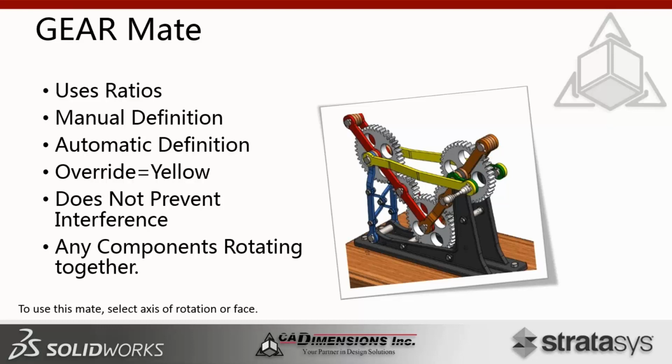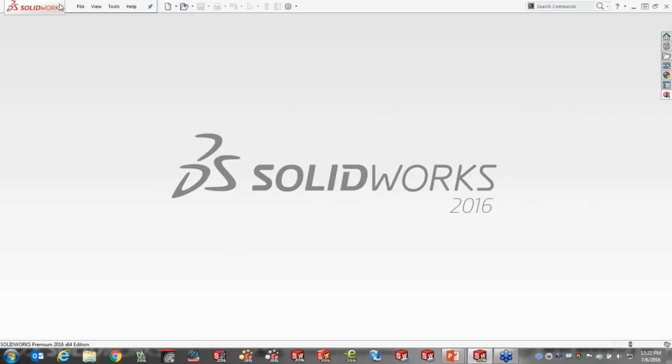A little note at the bottom, and this isn't necessarily always used for gears. Anytime you have components that rotate together at some ratio, whether they're touching or not, you can use a gear mate to do that. So let's take a look at gear mates.